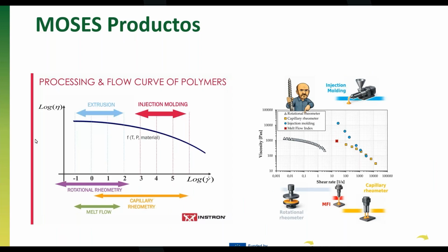And for example, in the case of PLA, which is a bio-based material, it is also really important, not only because of how the material will behave during the injection, but also because of the contractions that the material will suffer in the mold. You know, when you cool down a material, the final volume and the density of it change, and that also happens to the polymers once we freeze them in the mold. But let's keep on with the different examples in the next slides.